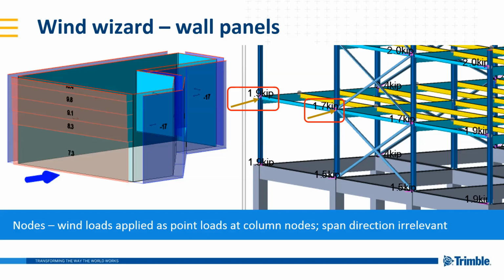It usually makes sense to keep these walls spanning horizontally or side to side because the columns can then support the wall themselves and you don't have to put in any extra dummy members.